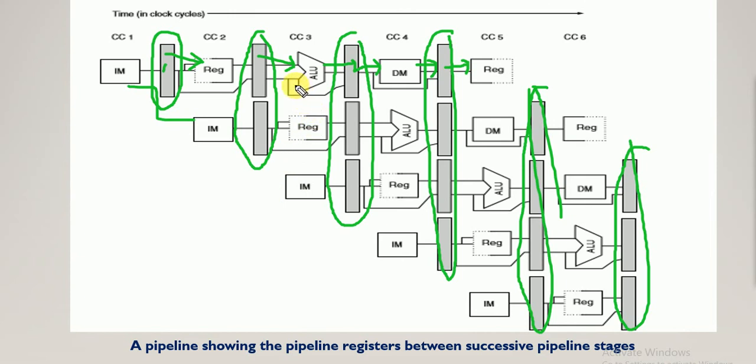Here you can also see from data memory to ALU we have a feedback, because if the ALU requires some data from memory, it will communicate with that, and this will be given back to the ALU, so this data will be executed in that particular clock cycle. So in every stage we have feedback, from register to ALU, ALU to data memory, communicated from one stage to the next stage, and from that stage to the previous stage also.